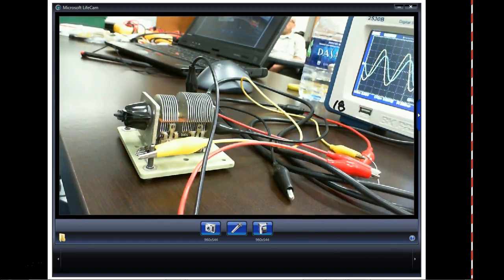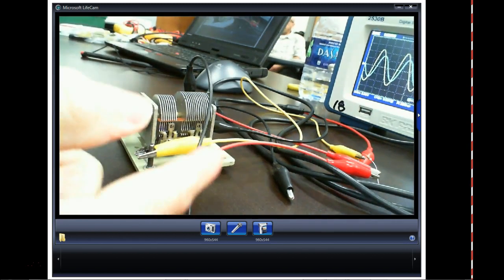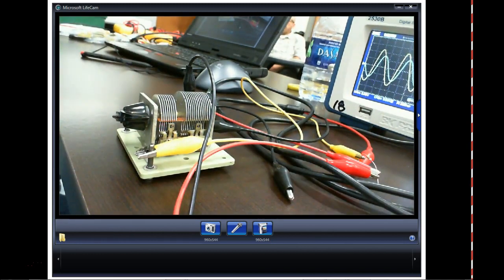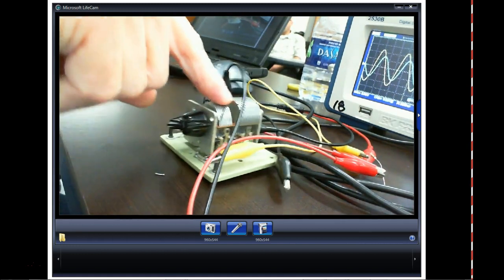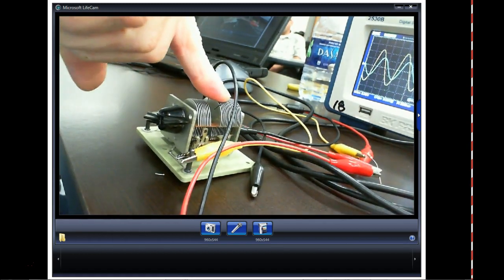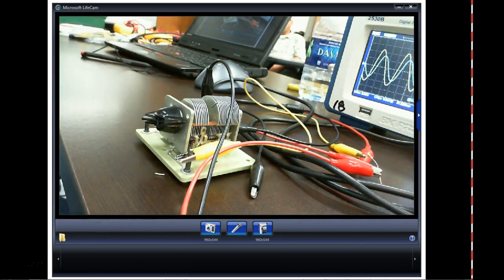So what do capacitors cause? Well, one thing, they cause a voltage drop. They appear to cause work. So if I was to measure the current flow in and out of the capacitor, I would have a current and I would have a voltage. So you'd say, okay, power in the capacitor would be equal to V times I, but the current is not flowing through the capacitor. The current is flowing in and out of the capacitor. So we are actually getting absolutely no work out of this thing right here. Capacitors don't get hot. If they don't get hot, it means they're not doing any electrical work.